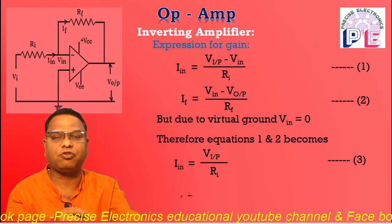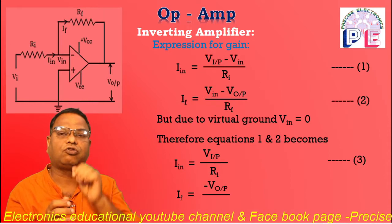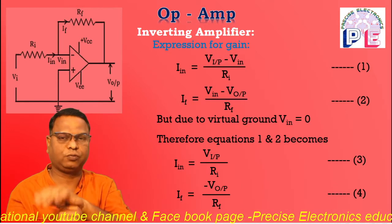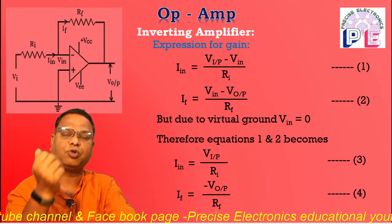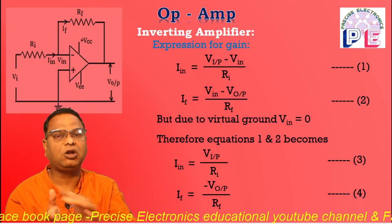Similarly, IF is equal to 0 minus V output upon RF, 0 gets cancelled. So IF is equal to minus V output upon RF, that is our equation number 4. Equation number 3 is I in is equal to V input upon Ri, and equation number 4 is IF is equal to minus V output upon RF.